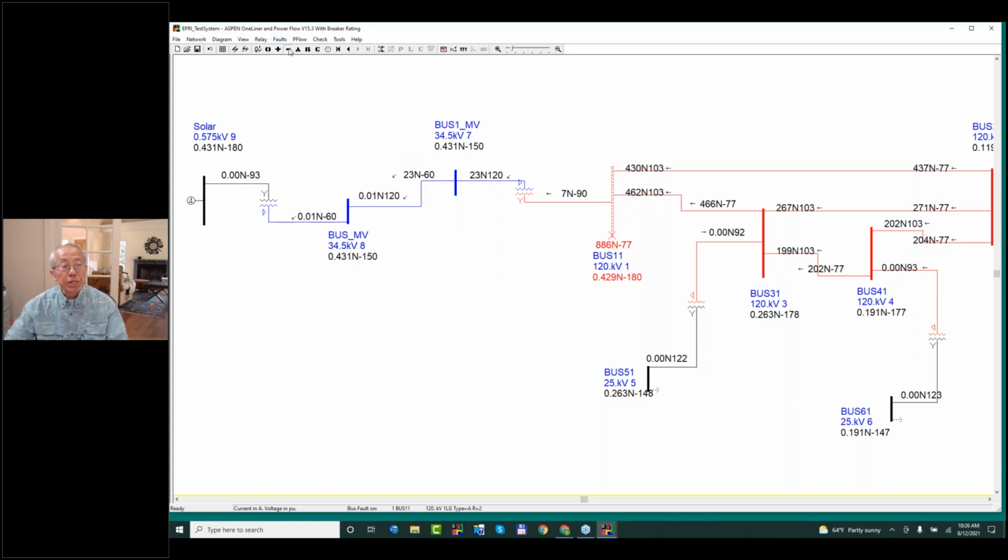And also I can look at negative sequence current. Now, if you concentrate on looking here, it also outputs zero negative sequence current. Okay, but this has to do with that negative sequence slope being zero. And so currently, none of these CIRs in North America, so far as I know, injects any negative sequence, because this injection of negative sequence is a mandate from the German grid system regulators only within the last year or so, maybe last year to 18 months or so. So the manufacturers are not making them quite yet, and maybe they are in Germany, but there are certainly very few here in the United States.